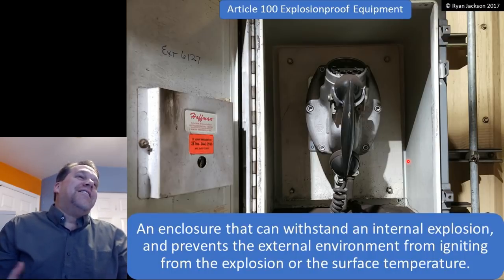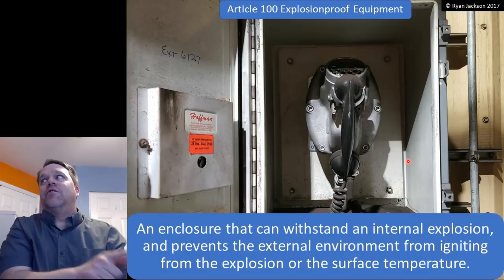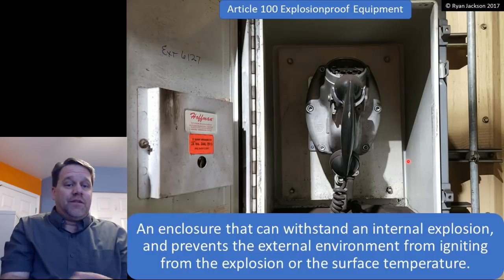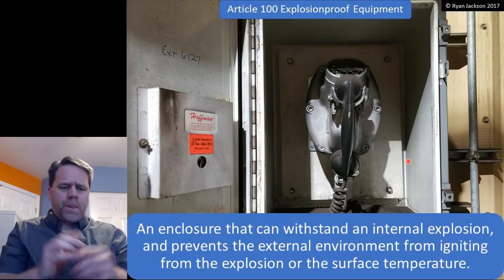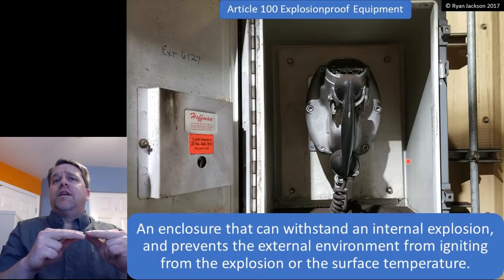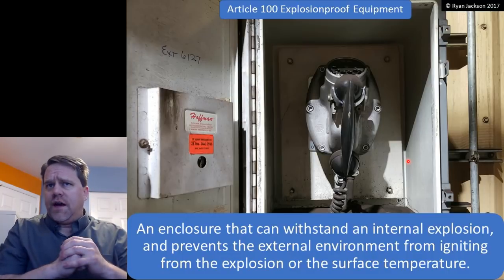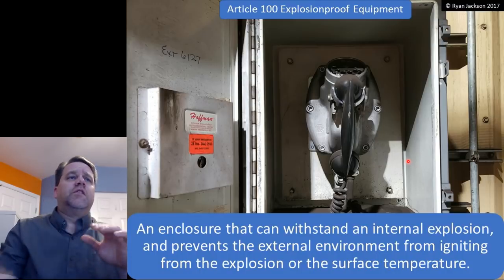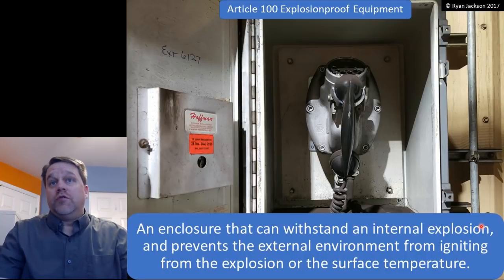And no, that's not what explosion-proof means. It doesn't mean that an explosion doesn't hurt our wiring. It means our wiring doesn't create an explosion, right? If I'm in an area that has ignitable mixtures and I have an arc, we need to make sure that that arc does not ignite the surrounding environment. And one way that we can ensure that is by using explosion-proof equipment. Again, that's an enclosure that can withstand an internal explosion, and it prevents the external environment from igniting from the explosion or from the surface temperature.